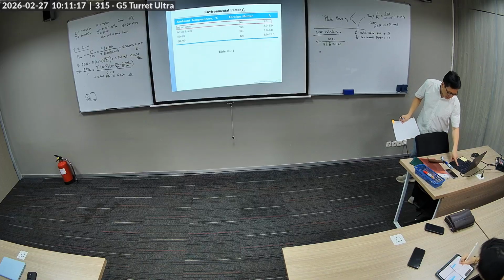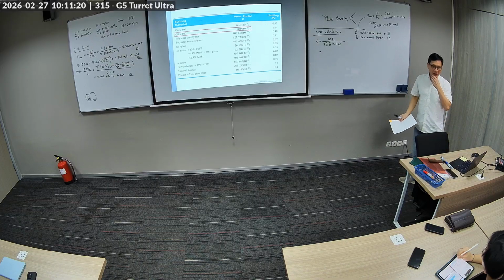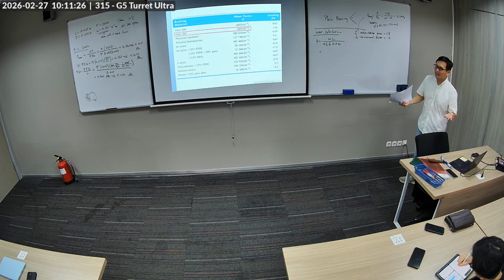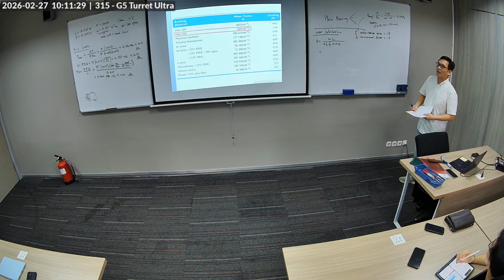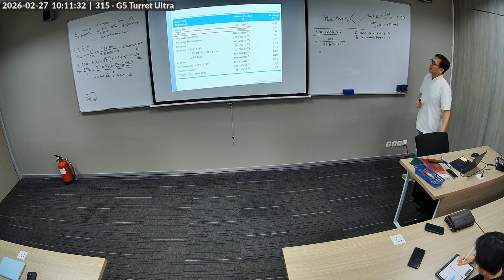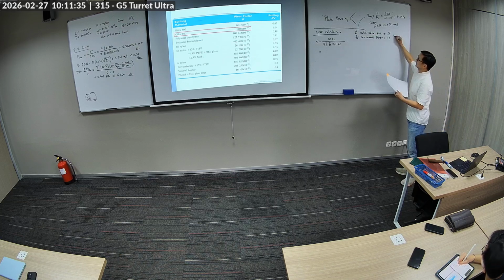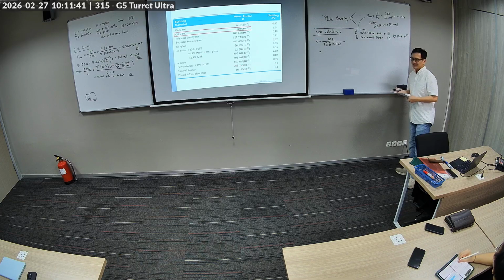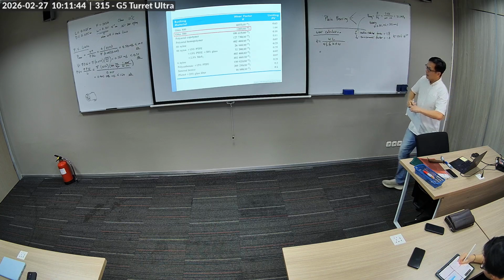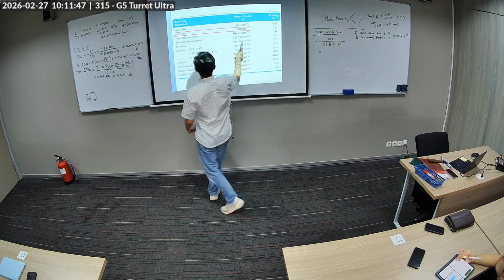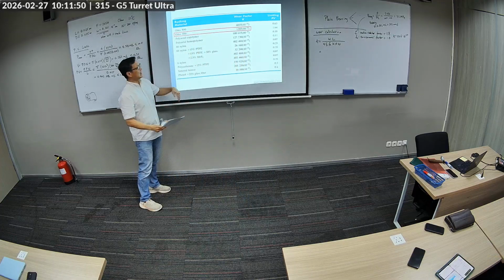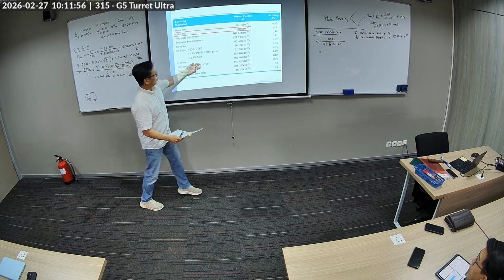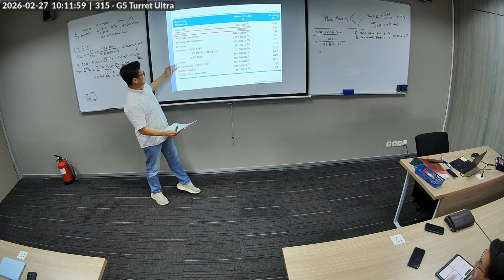One more thing we need to pull from tables. You're in engineering, so be prepared to look up a lot of tables, because industrial catalogs are full of tables. That's how they provide information. For oilless 500, the wear factor is 1207 times 10 to the minus 20. That's just a multiplication factor. A bigger wear factor means it wears harder. A nylon, for example, will have this much wear factor.